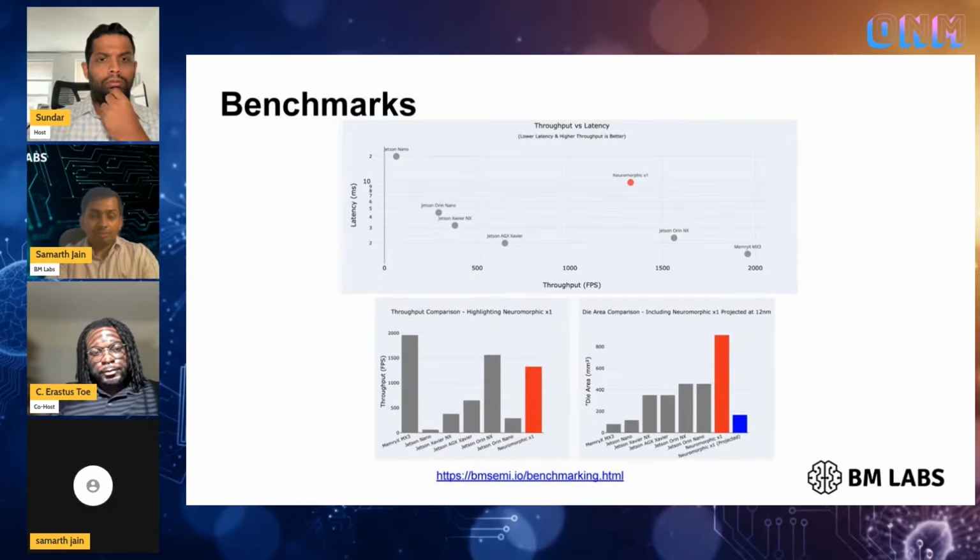So that's where we started. This technology is cheaper because you can get the same performance at higher nodes. The reason is that the SRAM cell you make needs at least 6 transistors, whereas this one cell, this 1T1R, can do compute and store at the same place. So you save space, right? And that's why you can afford a higher technology node to achieve the same performance, which cuts down your cost. And our technology is CMOS compatible, so you don't need any fancy integration. It's all on CMOS fabs. Our chips are fabricated at SkyWater, which is a US-based fab right now. It's completely CMOS compatible, as I mentioned, like a capacitor, right? So it doesn't need a special process.